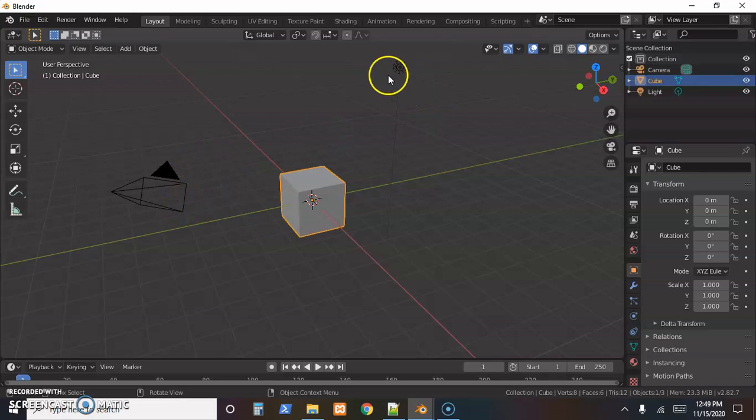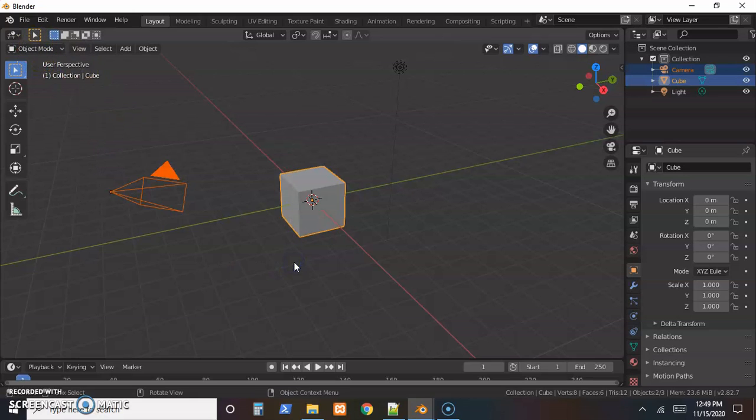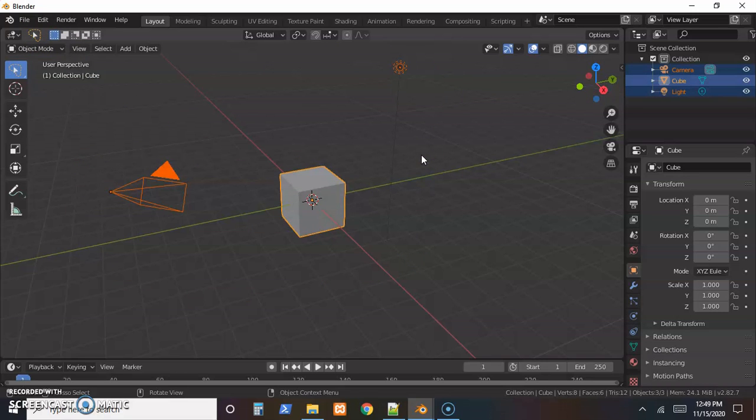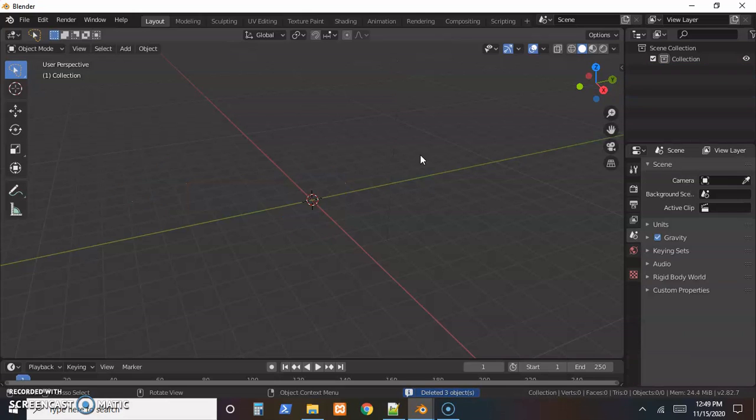So here's the default setup. Obviously not going to need a camera or lighting, so I'm going to delete the default ones. And by default, it's set for a box select. I prefer the freeform selection. So if you put your cursor anywhere in the middle and hit W, it'll scroll through the different selection types, and then the freeform selection will be especially important when we go to apply materials.